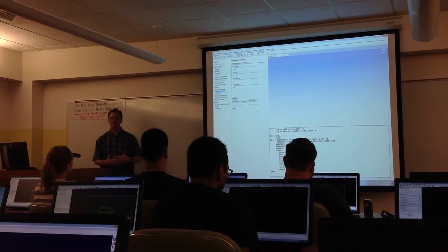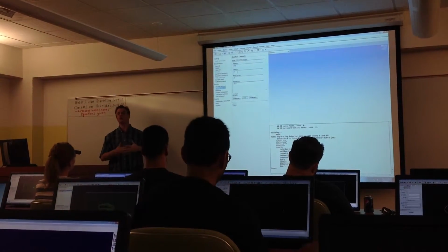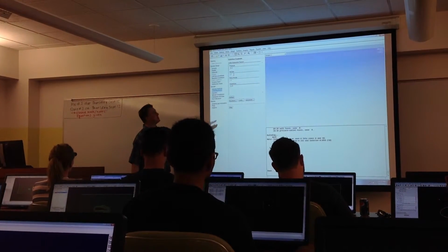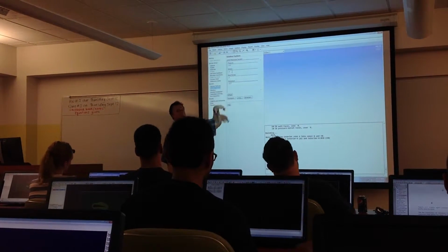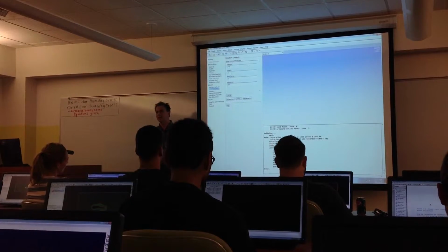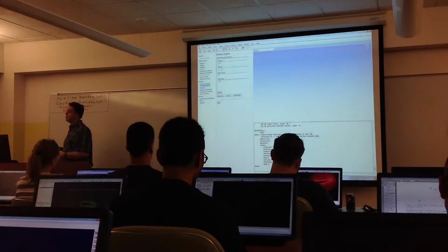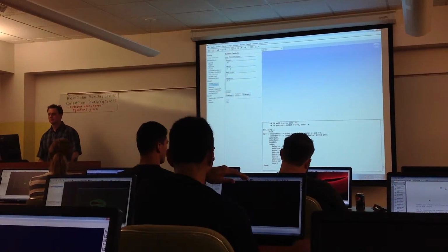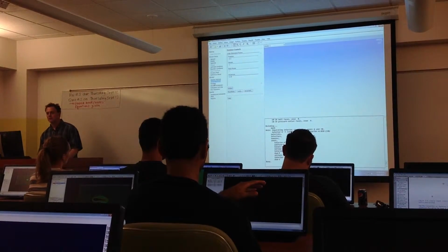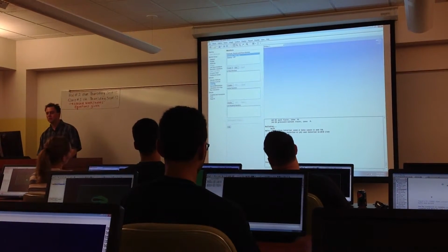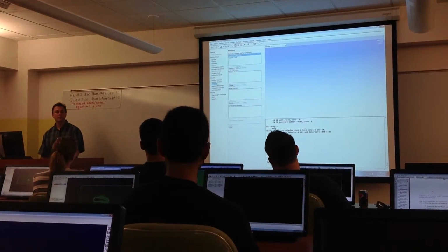As the solution progresses, it makes things more stable. It takes longer though. If I reduce this to half of its value, it would probably take twice as long to get to the second point. But you'll do it in a more safe way. Once the solution blows up, you've lost it.